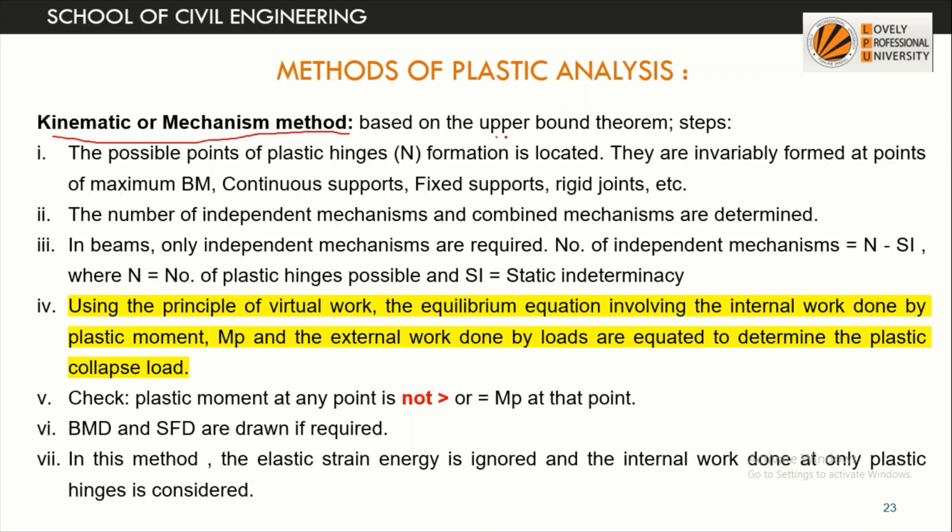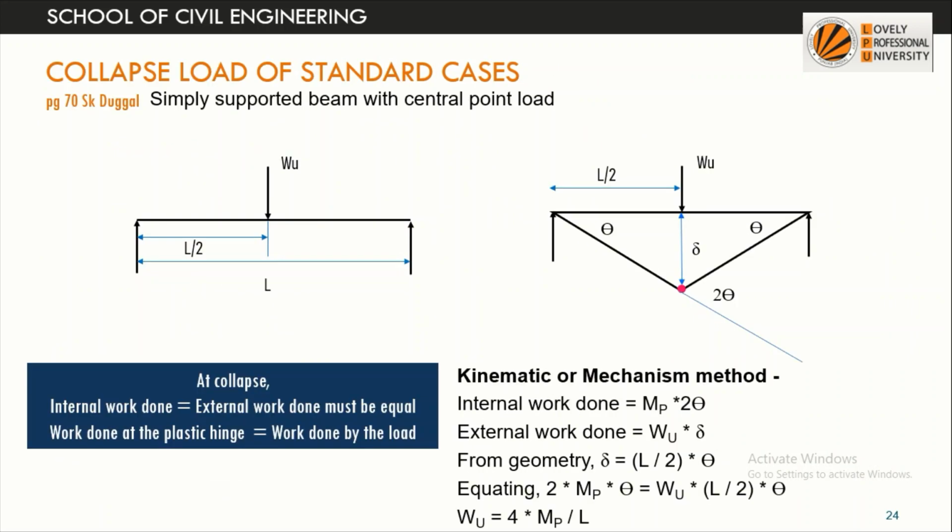It is based on the upper bound theorem, in which we use the principle of virtual work, where we equate the internal work done by the plastic moment with the external work done by the load. So it is basically a virtual method in which internal energy is equated to the external work done. External work is done by the load, and internal work is done by the plastic moment. So let's see how to solve the same problem.